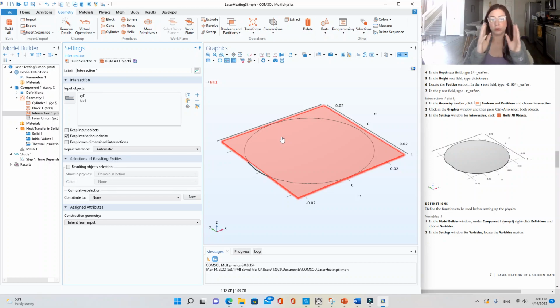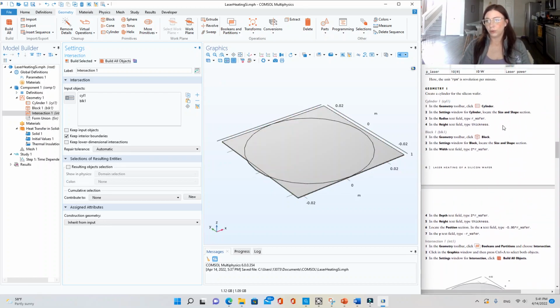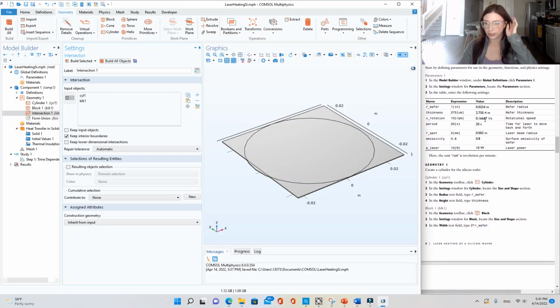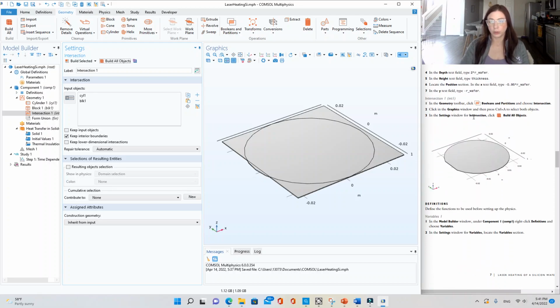It grows radially, and you have a super long boule of silicon, and then you put it on its side and slice it 275 microns thick. Well, it would be thicker than that because then they get polished on one or both sides. And then it has a flat end, which is typically how you orient it upward in a cassette for processing through the fab.